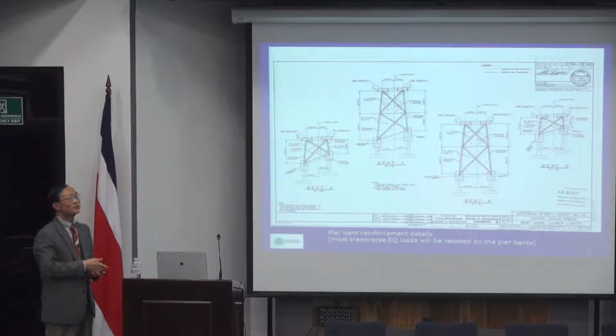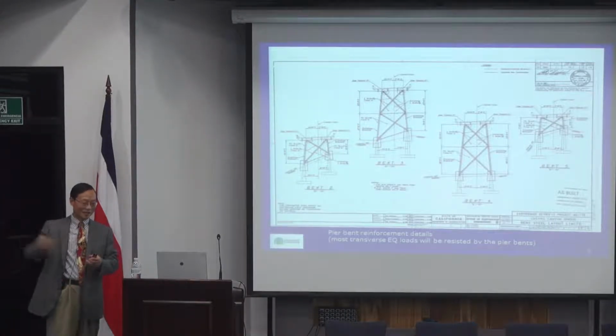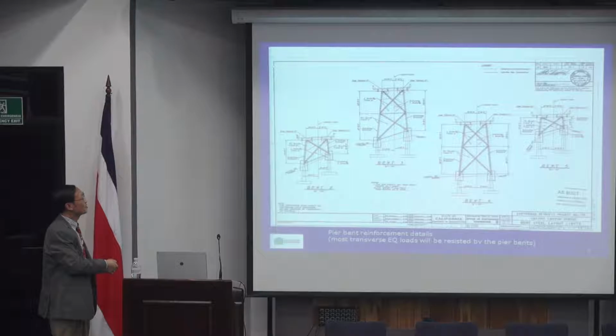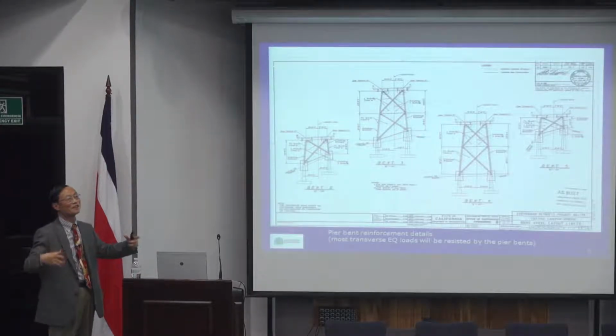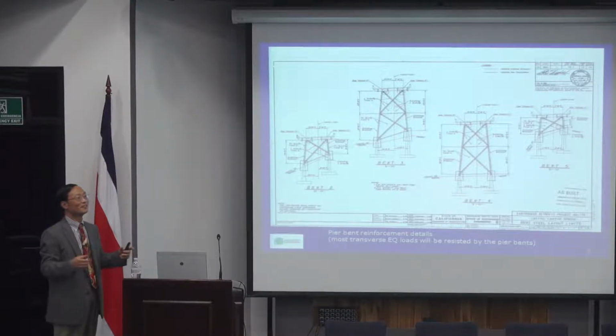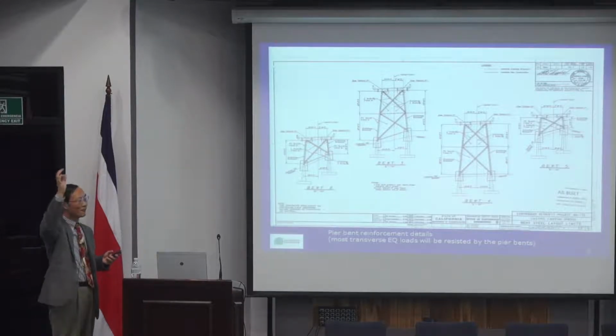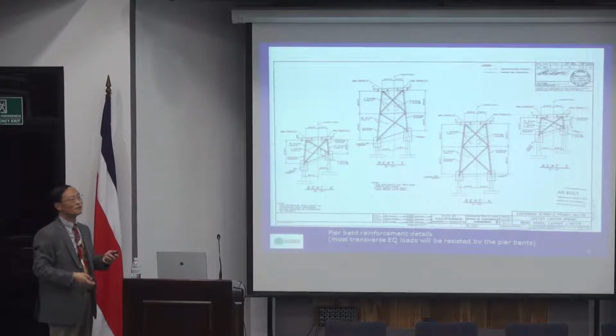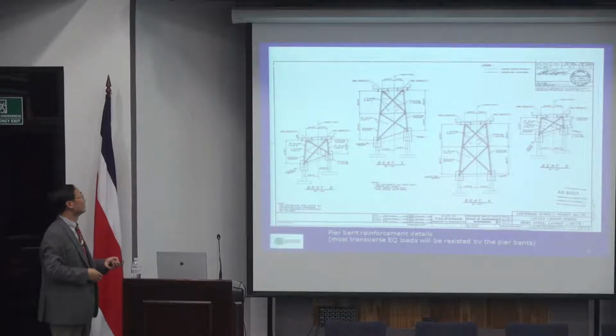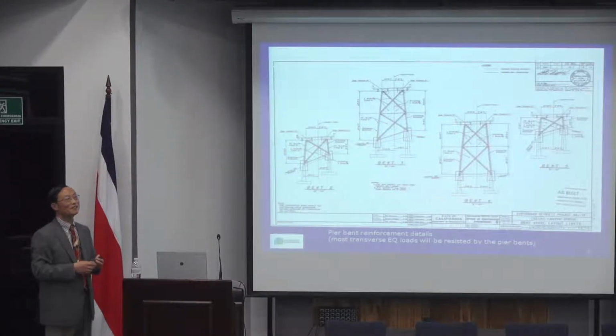That's why you need to introduce another direction. In these, typically you can have this very rigid, you can resist twisting. At the piers, you can provide another connection to the pier, so that once you have another direction, the twist will become another issue. Actually, twisting at connections is very essential.